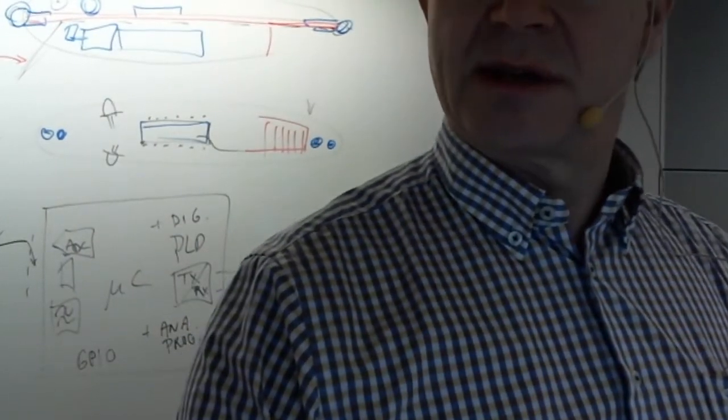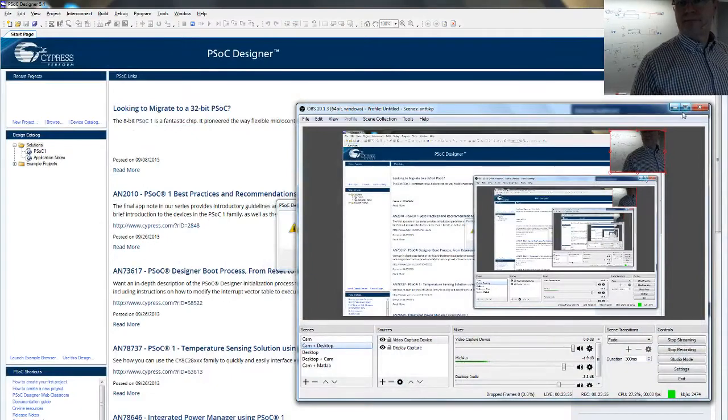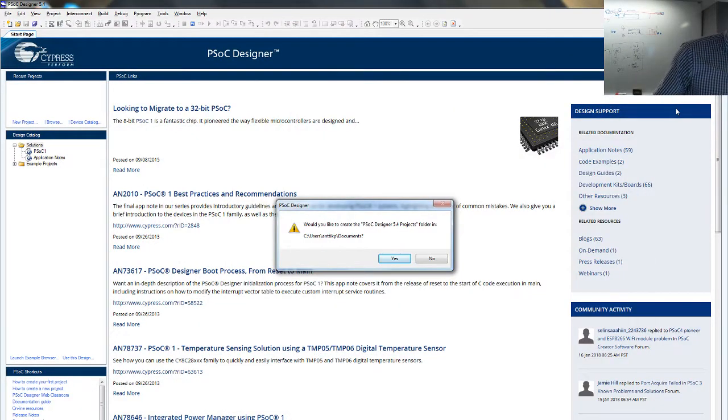And how to change it? Basically, we would love to have a very small screwdriver here. Lift it very gently on the other end first. Yes, we need screwdrivers here. Yeah, good, excellent. So not with the hands. If you force it, then it usually bends the legs, and you can bend the legs only once. There's also a tool for that, but the small screwdriver does the same trick.